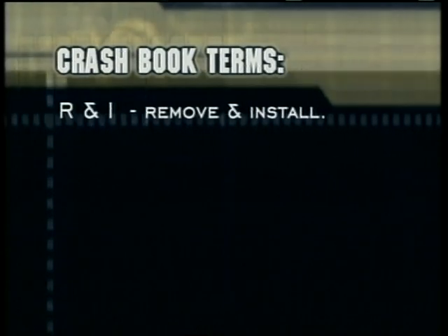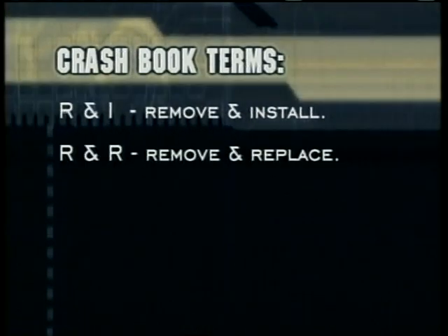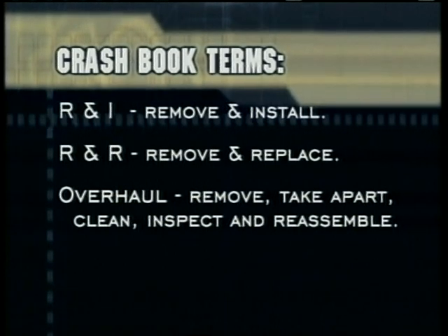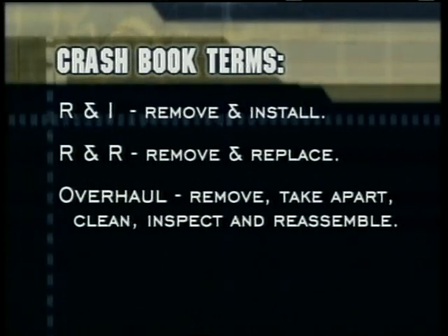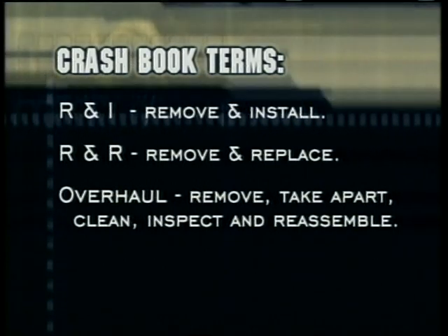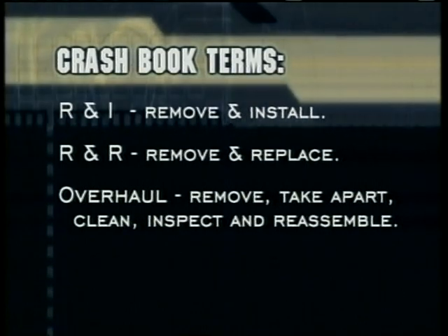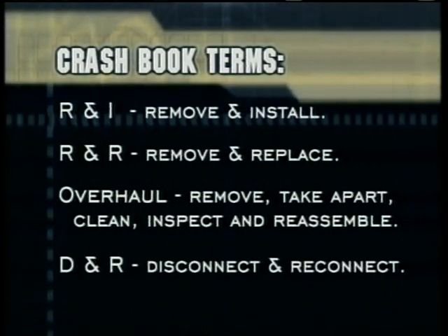Some terms found in the crash book that you'll need to be familiar with are R&I for remove and install, R&R for remove and replace, overhaul for remove, take apart, clean, inspect, and reassemble, installing, replacing, and adjusting parts as needed, and D&R for disconnect and reconnect.